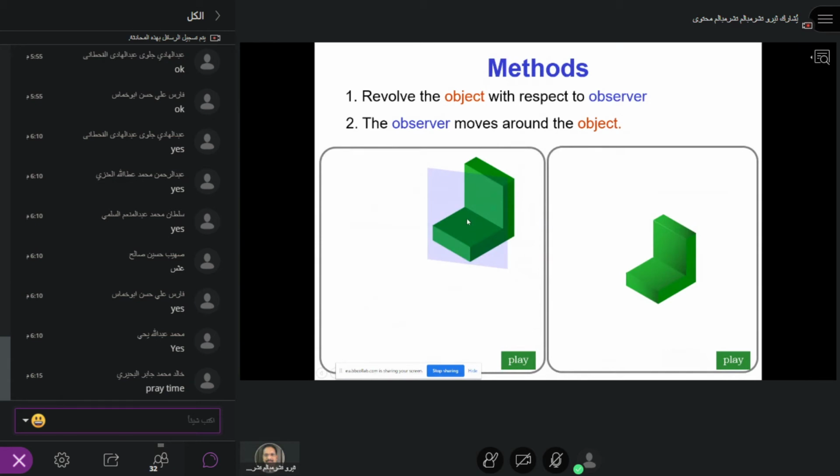This is the object, all right? So this is a three-dimensional view of the object. I want to show it in a two-dimensional drawing. So what I'm going to do, I see the front view, right? When I see it from here, keeping my eyes parallel, these edges will be parallel to my eyes. So all I can see is this surface, correct? These edges I can see.